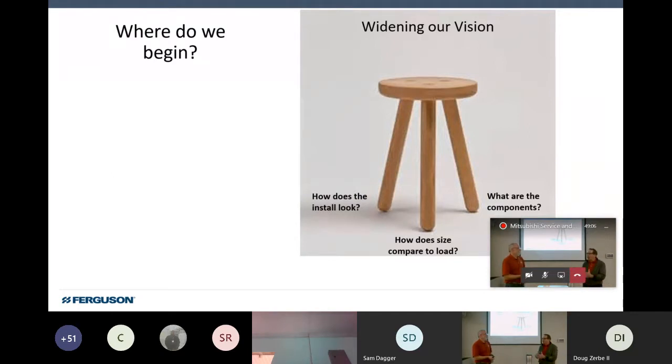So what we're saying is take the blinders off. When you pull in, you should know what you're dealing with totally, as a whole. We need to know whether it's a ported unit. Is it a branch box? Is it a one-to-one? Is it a multi-zone head? What are the controllers? All of those things today will affect the way that the system operates. You burn up too much energy with blinders on, just looking at that unit going, I wonder why it's not cooling. Let me put my thermometer on it. Let me go out to the truck and get my humidity meter.